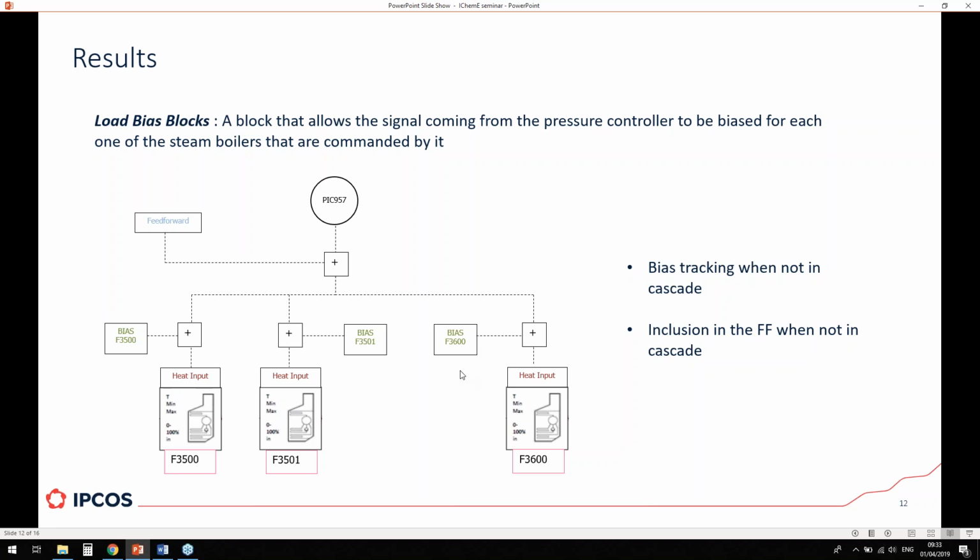That way you can, for example, choose one of those boilers in the north and say, okay, I want to produce a little bit more with this boiler. The moment I start increasing this value, the other boilers start reducing production to match the same amount of steam produced.